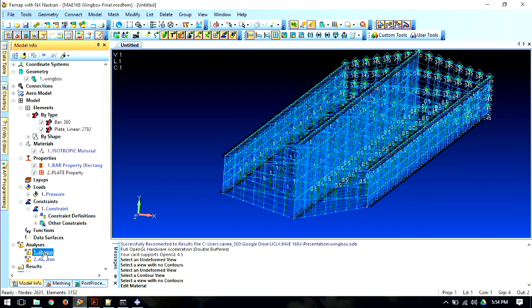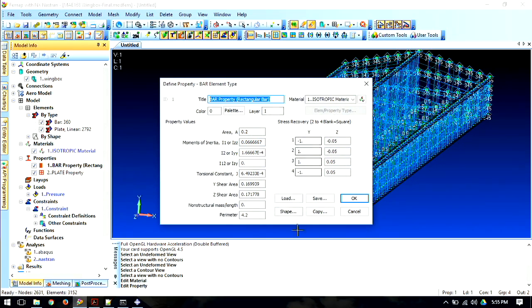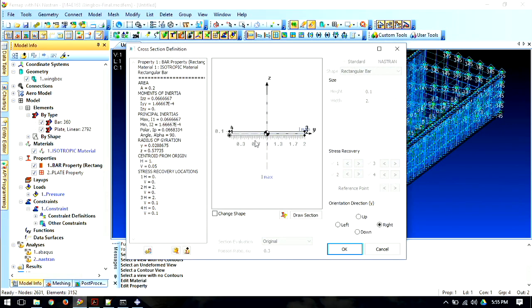Can you discuss the beams more? The beams, how they're used. Yeah. So, as I was talking, the beams are used to represent the caps of the spars only. So the I-beam has the web, which is the vertical, and the caps. And so in the beams, I have my shape here. So here's my Z direction. Here's 2 inches, 0 to 2, and 0.1. And that's where you input it. And that's what you see here. I rendered the beams in here, so you can actually see the beams. So it's more to help you visually and it'll help you with orienting this Z direction of these elements.